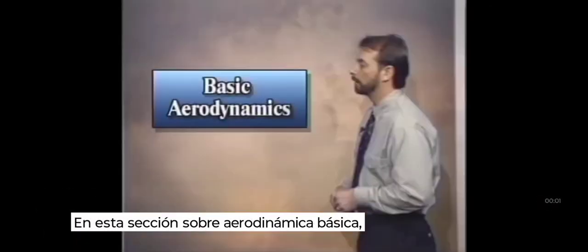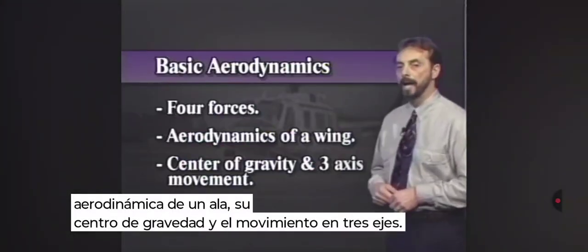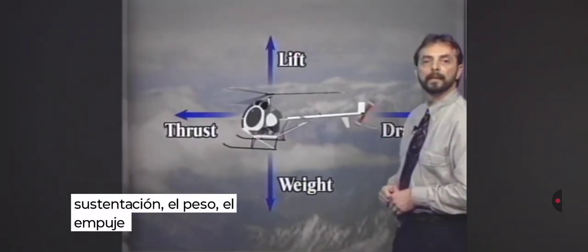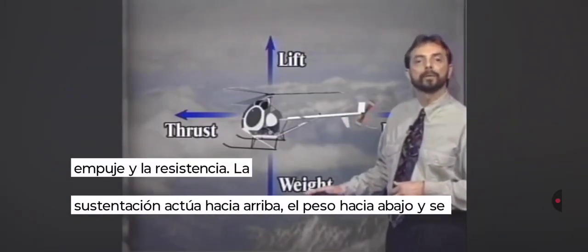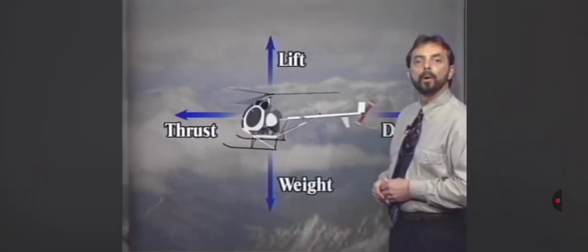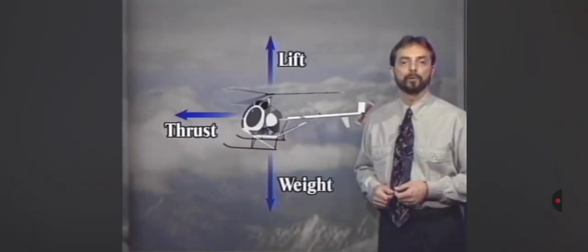In this section on basic aerodynamics, we'll briefly discuss the four forces, aerodynamics of a wing, center of gravity, and three-axis movement. The four forces include lift, weight, thrust, and drag. Lift acts upwards. Weight acts downwards, opposing lift. Thrust pulls forward, and drag acts in a rearward direction, opposing thrust. When the aircraft is in straight and level flight at a constant airspeed, lift equals weight and thrust equals drag.